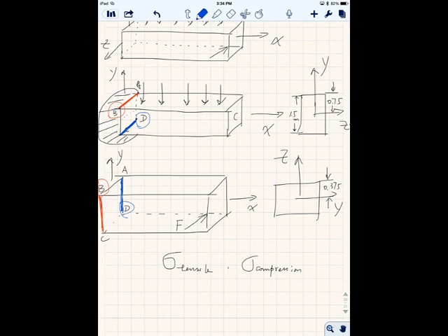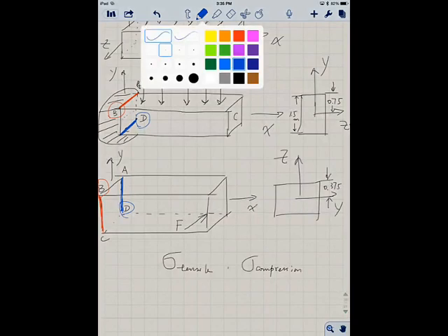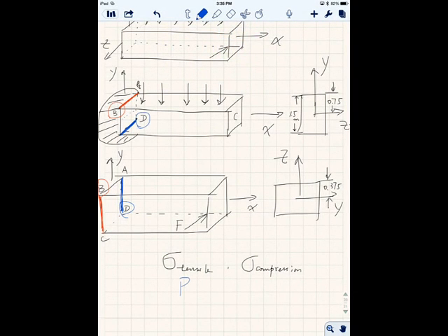So point B is on the maximum tensile stress of AB due to the distributed load, but point D is under the maximum compressive stress line on the distributed load. At the same time, they are on the maximum tensile and compressive loading because of the concentrated load as well. So that tells you, very possibly, maximum tensile will be at point B, maximum compression is at point D.